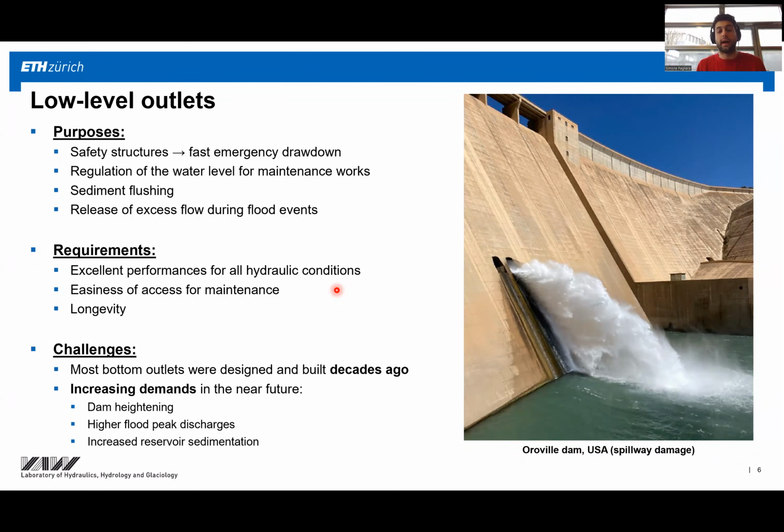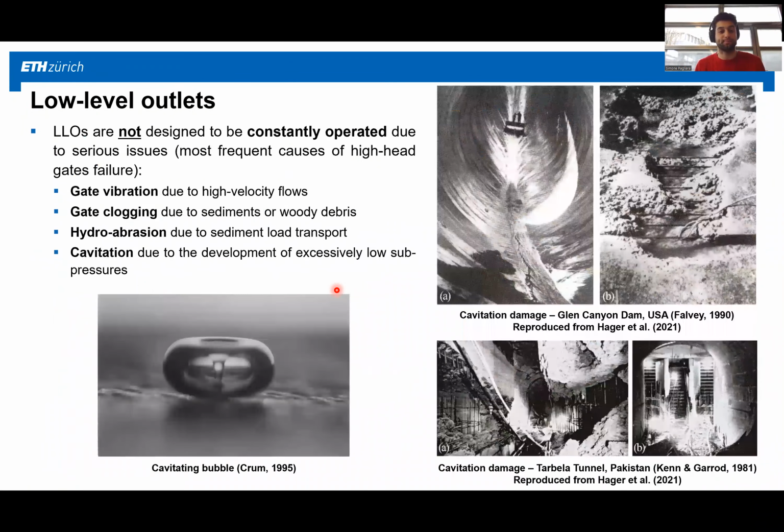So higher flood peaks, higher reservoir sedimentation, and dam heightening to tackle these problems. And so low-level outlets will be more and more stressed in the future. And the bad thing is that most of them have been built decades and decades ago, so they need to be updated. So looking at cavitation, as I said before, low-level outlets are not meant to be used constantly due